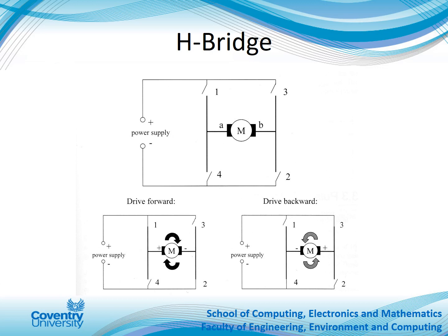When you're using the power amplifier chip, the positive and negative inputs, like the X and Y pins, are electrically decoupled from the motor, so they can be directly linked to the outputs of the microcontroller. The direction of the motor can be specified by the software, for example by setting output X to logic 1 and output Y to logic 0. Since X and Y are always the opposite of each other, they can be replaced by a single output port and a negator, and then the rotation speed can be determined by the speed input, which is linked to the pulse width modulation output.